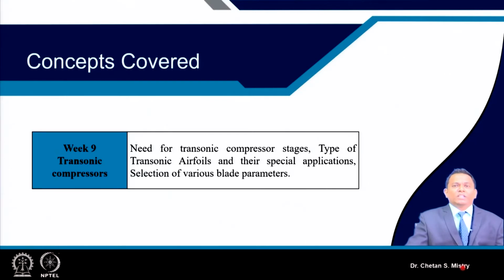This is of a special kind, with good aerodynamics and gas dynamics understanding, with which we realize that if we are able to manage our flow at the entry, that means at the leading edge of our transonic aerofoil, it gives us benefit. Initially we felt a sharp edge gave benefit in anchoring our shock.